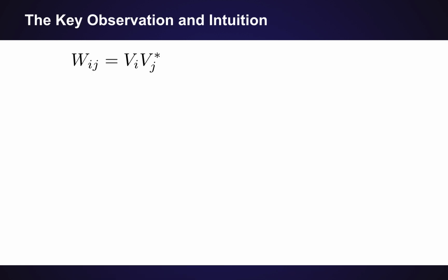Okay, so let's go back to this constraint. As we have seen, if we are able to convexify this constraint, we are going to have a convex problem. The key thing is that we cannot keep that constraint as it is, because it is non-convex. So what we want to do is to find a convex representation of this constraint, which is by design going to lack some of the information, but is going to keep as much information as possible about the mapping between the voltage variables V and this lifted variable W.